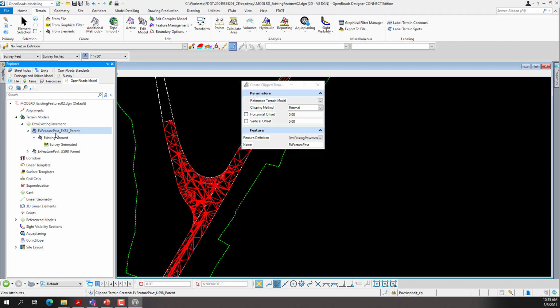In previous exercises, we always deleted the parent or deleted the clip. We don't want to do that, because if we delete the parent clip, then we can't update, or we don't have a parent-child relationship between the new clip that we have. So we're going to turn off triangles on the parent after we create our child. So let's do that now in this exercise.